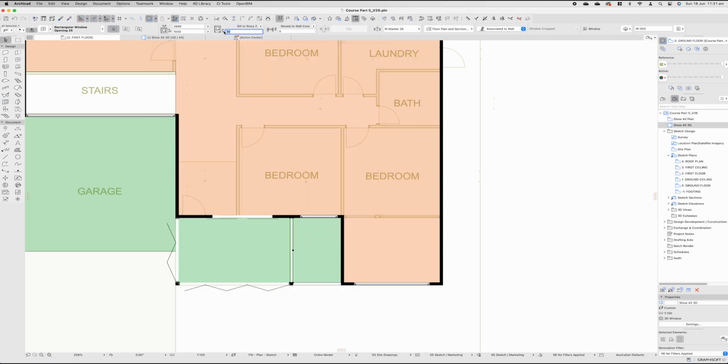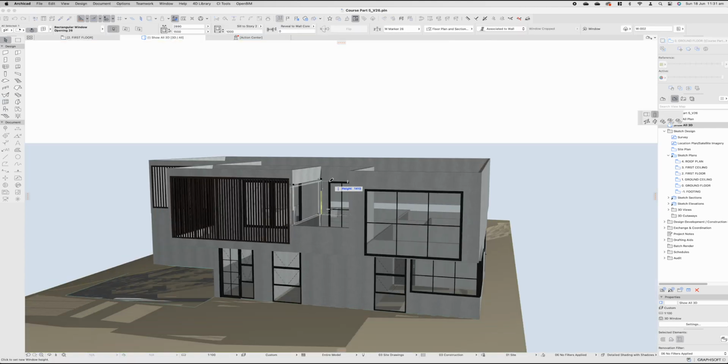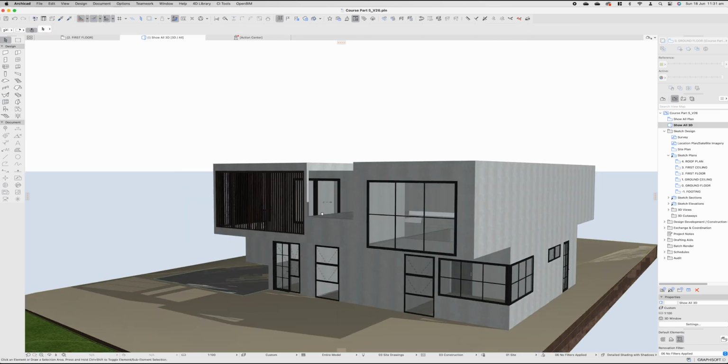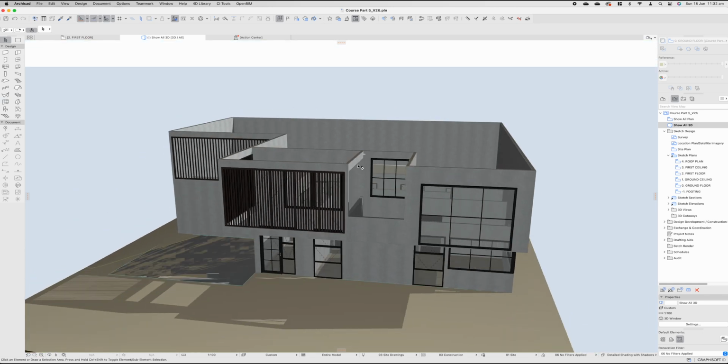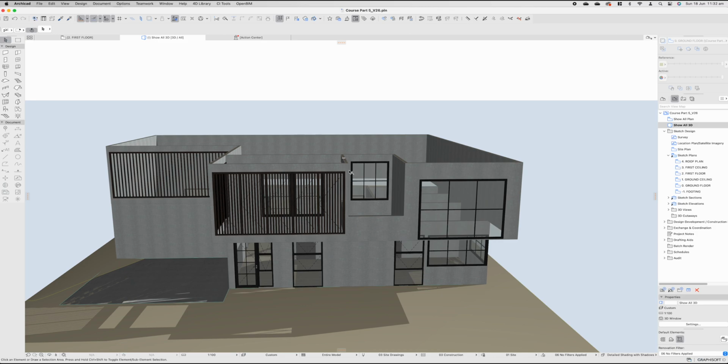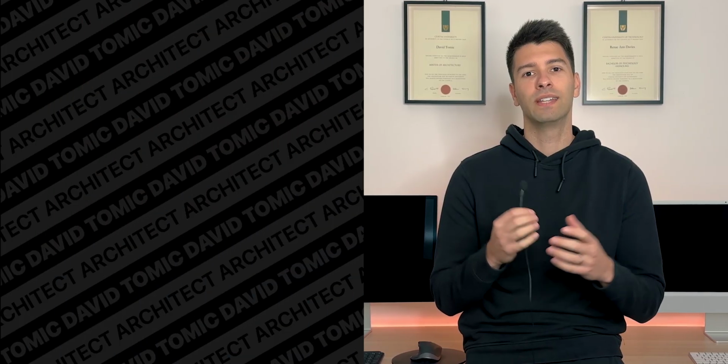Make sure our sill is 1 meter, jumping into 3D and aligning our sill height with our window heights over here. We'll see that we've now created an opening, allowing that light to come through, but yet connecting our wall back to our main house so it isn't flapping around in the wind and we don't have to tie it across here.